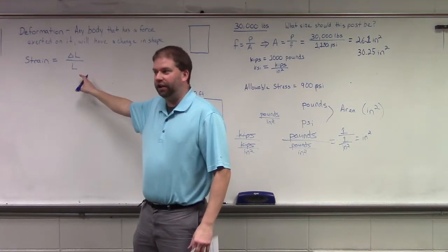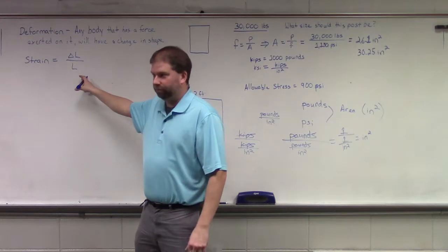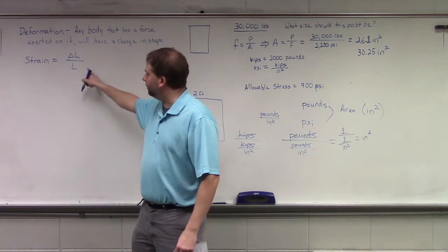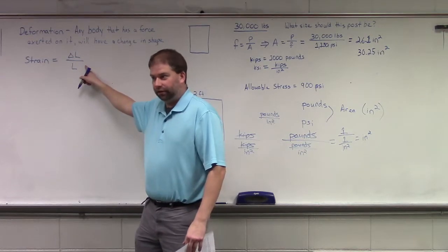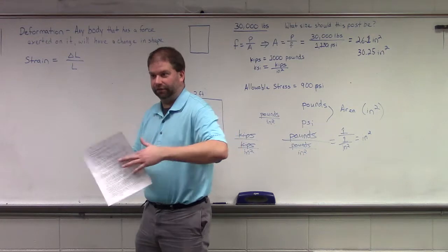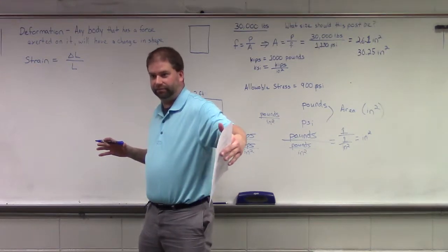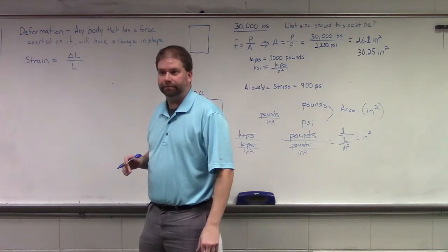What happens if our strain is big? It's going to fail. We could definitely end up with failure, right? In fact, if we have strain greater than 1, what does that tell us? We've increased that length by 100%. So it could be very, very bad depending on what our material is. All right?